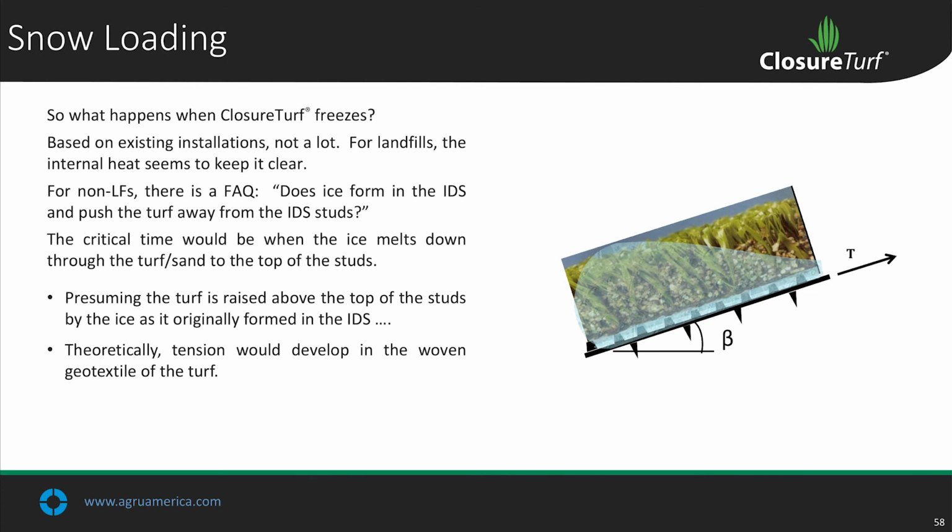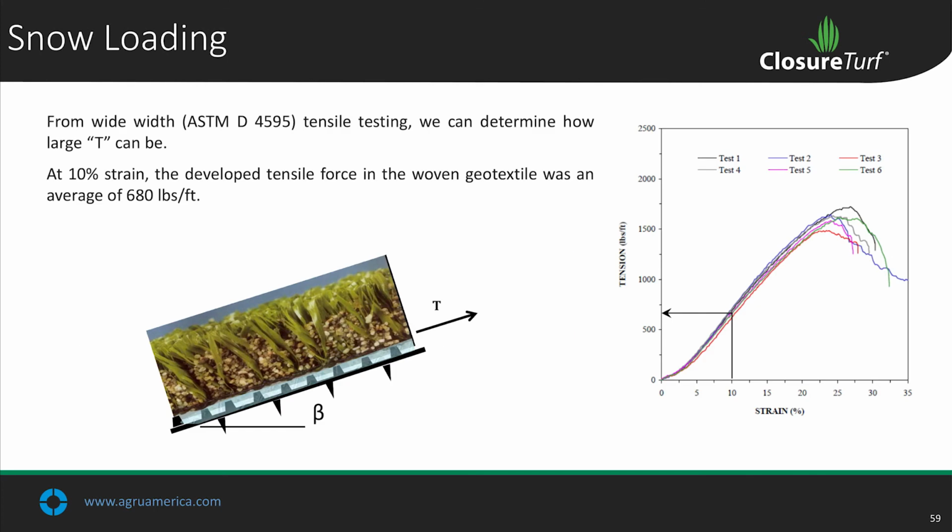From wide width tensile testing of the turf, you can determine how large T can be. So let's use a 10% strain, and the developed tensile force in the woven geotextile was an average of 680 pounds per foot. Still in an elastic regime here. When the tensile force is released, it might have some residual strain left, but overall that should be repeatable.